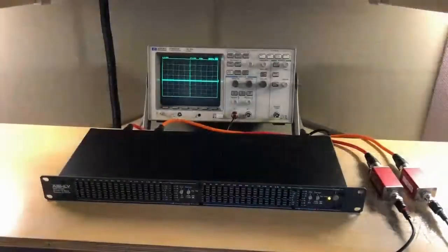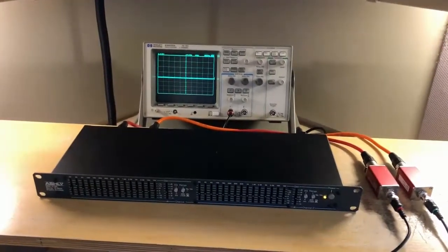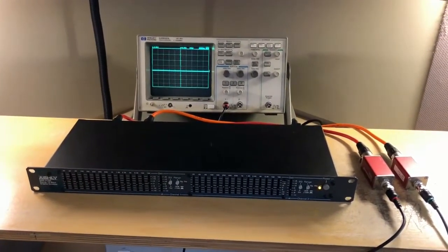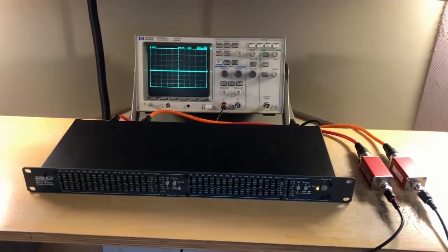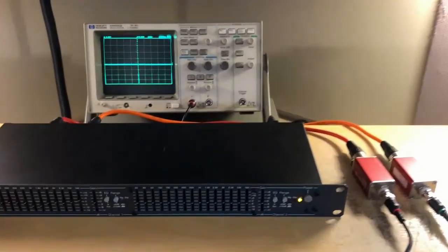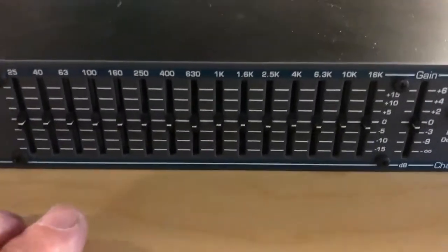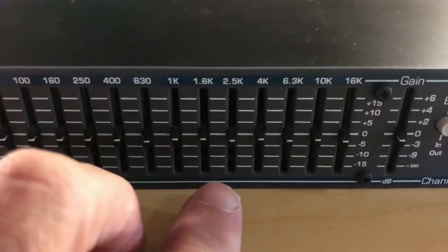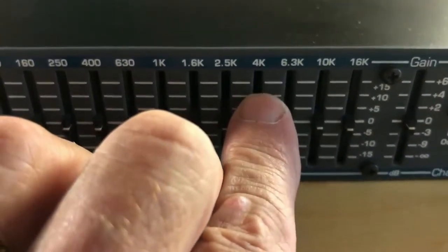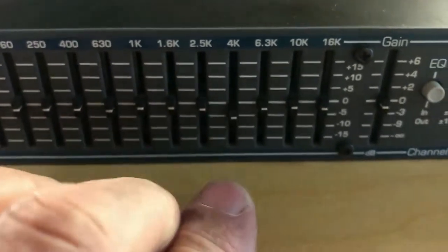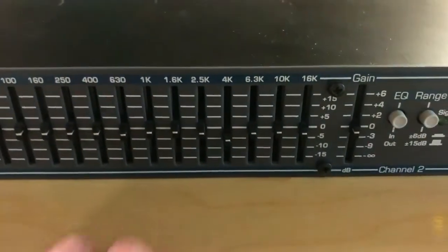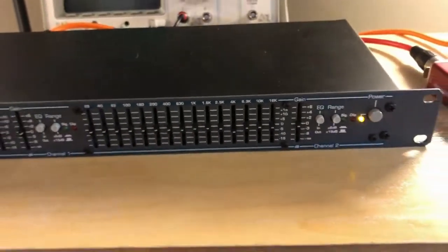We'll run a frequency response on a real-world device under test, an Ashley professional equalizer from a sound reinforcement system. Now, to make things interesting, we're going to deliberately move the 4K attenuator just slightly off its center detent to see if the CAT can pick up that dip in frequency response.